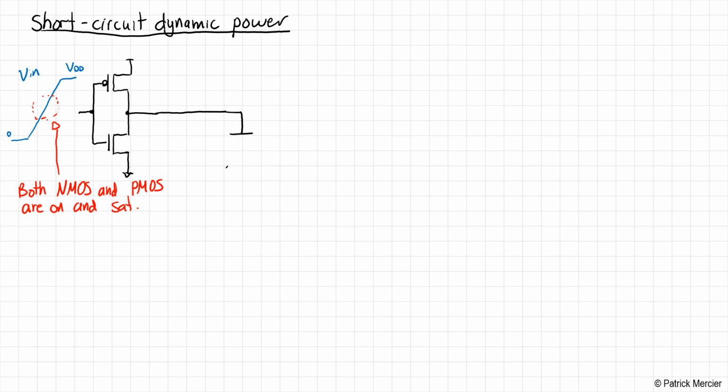So let's just make a note here. Normally we have some sort of model of our output load capacitance here. And because that load capacitance is finite, if we have a ramp at the input, even if we had a perfectly straight line at the input, we're still going to get a ramp-like signal at the output, where this is VDD and this is ground or 0. Okay, now leave a little bit of space in between the inverter and CL. I'm going to add another element there shortly.